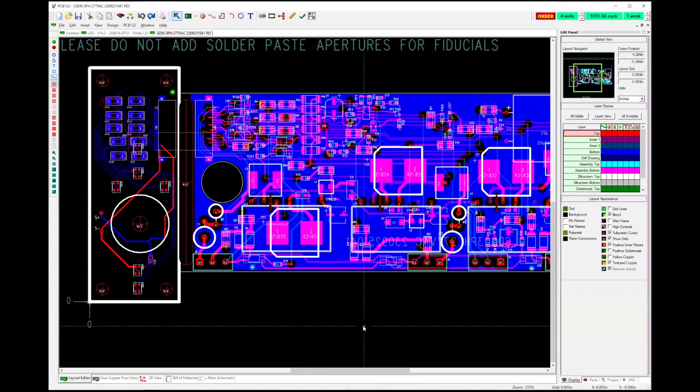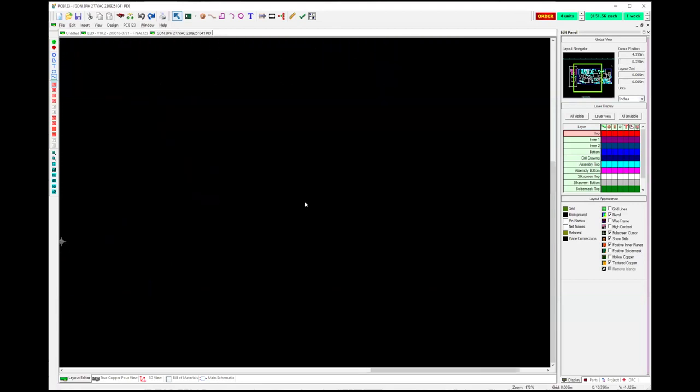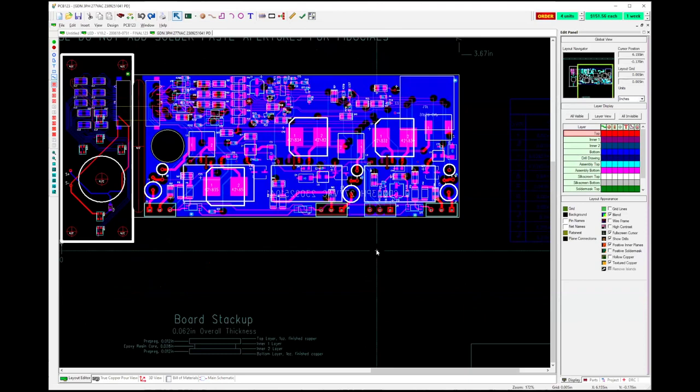That's probably not recommended with this tool, because, well, with any tool really, where you have 2 different voltages on an inner layer, simply because once you define a layer to contain those two different voltages, you're required to keep track of that in your head.